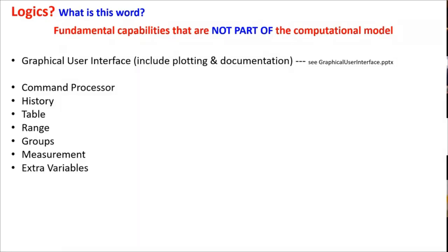So you might have, like, you're doing a crazy model with a magnetic field, and PFC doesn't kind of know about magnetic fields, but you could implement a FISH function to provide a magnetic field behavior. And so you might want to store like dipole, which I think is a vector, and you want to have the value of the dipole for every single ball.